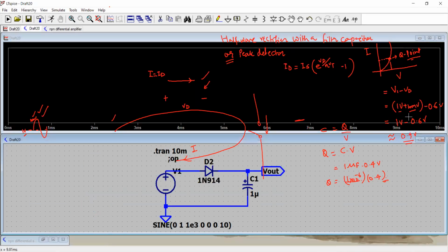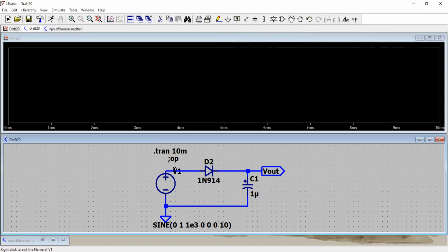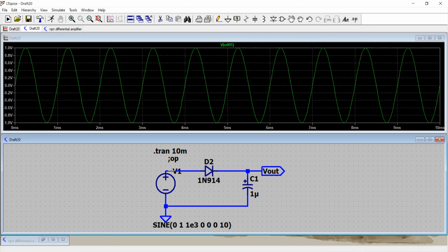And here I have this graph. Before I show you the waveforms, let's clear all the drawing. We are all set. First, come back to the schematic and see the red probe. I click enter. It's now a pure applied sinusoidal wave with the DC voltage level of 0 volt, and on top of it goes 1 volt up and 1 volt down. With that, now I am going to plot the output voltage, which you can see now, the blue line.